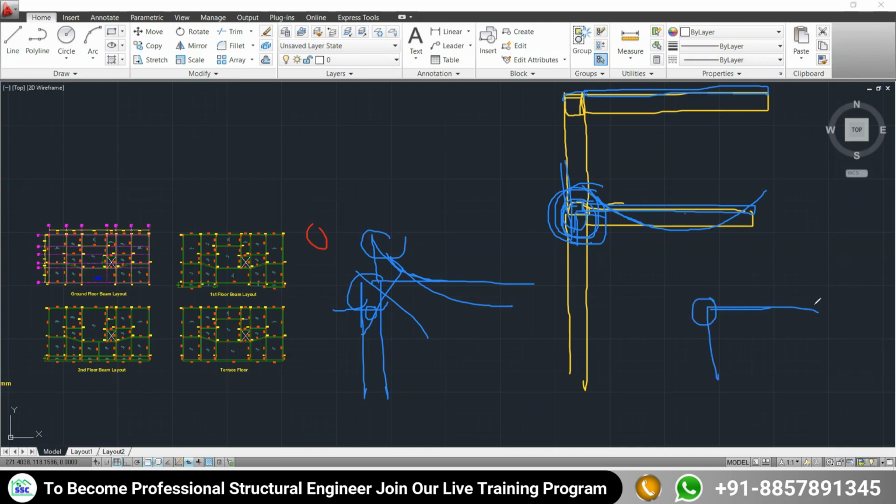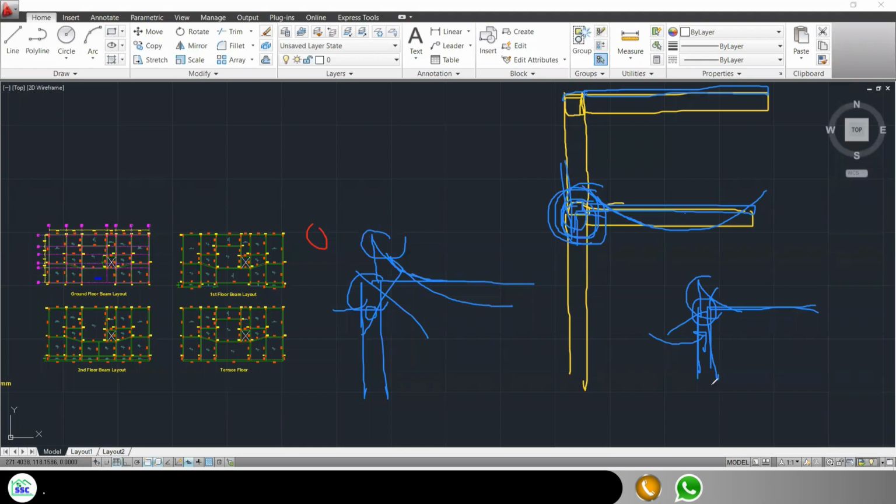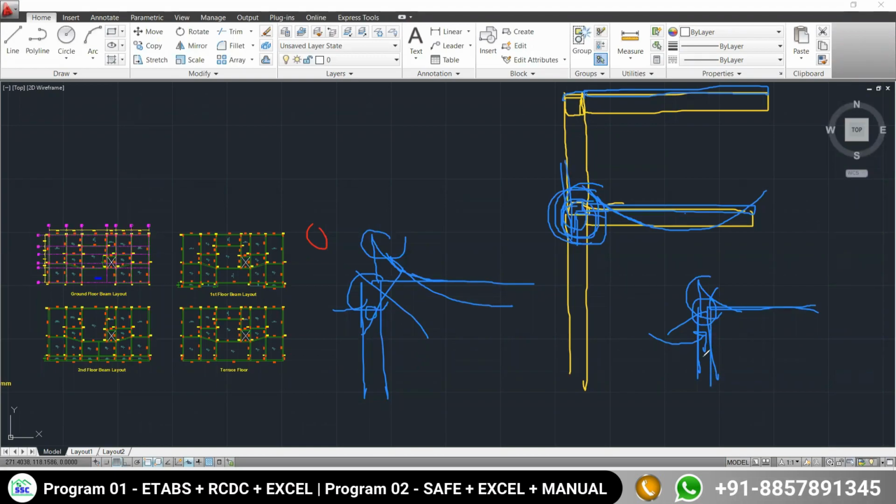We call this beam a fixed beam, and over the column and beam support there will be development of negative moment, and that moment is going to be carried by the connectivity of your beam and column. So we cannot make this column pinned. But in any situation, if you want to make this column free from carrying the moment, you have to make it as what?